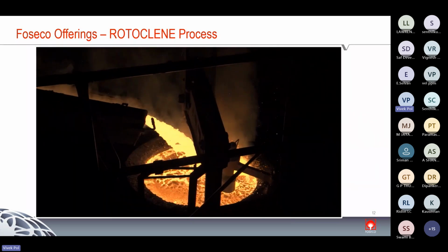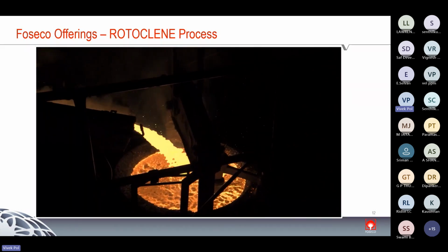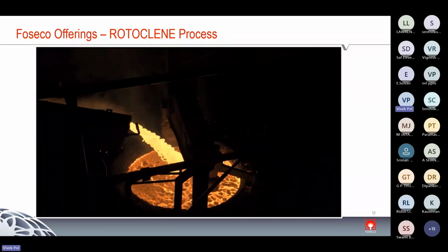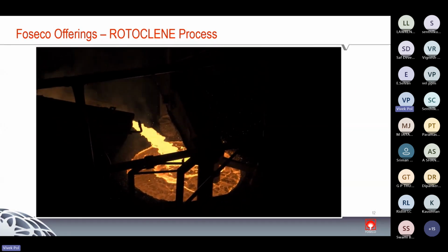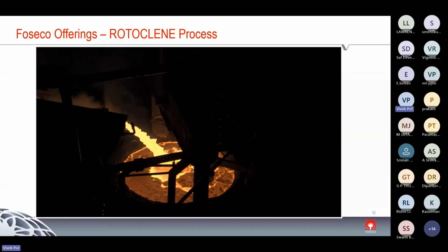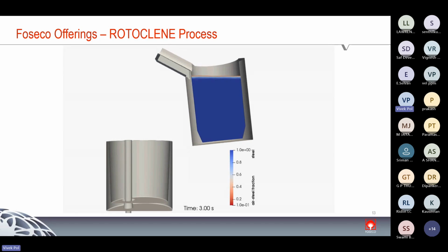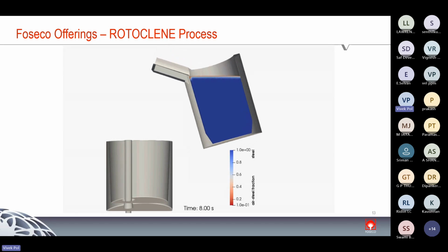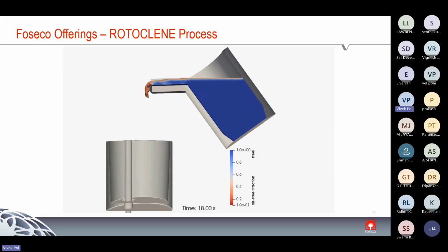Therefore the defects associated with this operation also come into the casting. However, there are some processes which help to reduce inclusions. For example, in steel, argon purging is one of the solutions, but those have some limitations, and that's why advanced processes are required so that we can effectively remove the inclusions and bimetallic films.